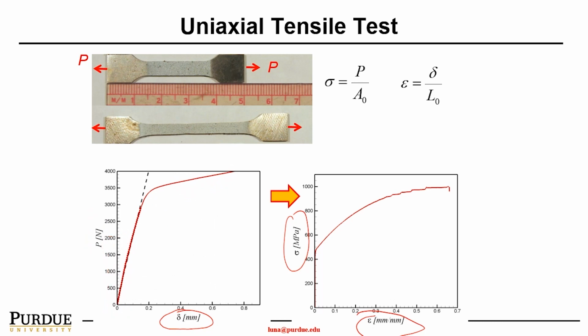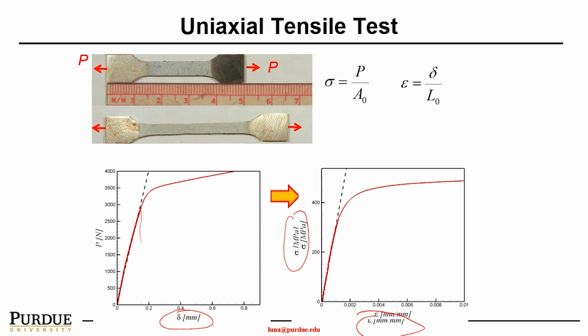we have very linear behavior at about 0.2 deformation. And if we focus on this area, as we have shown, under the stress the strain will be very, very small. So we have a very small linear behavior area, where a very large stress induces a very small strain. And the rest of this area will be nonlinear.